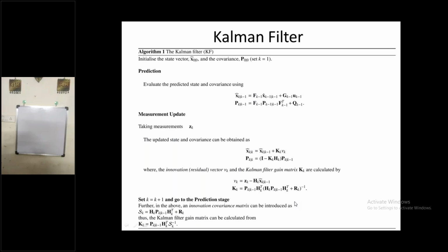In general, people use triple redundant sensors in real life applications. That means you are using 3 sensors to measure the same single output, let us assume the speed of a DC motor. Then you have to use some logical fault detection and fault isolation as well.